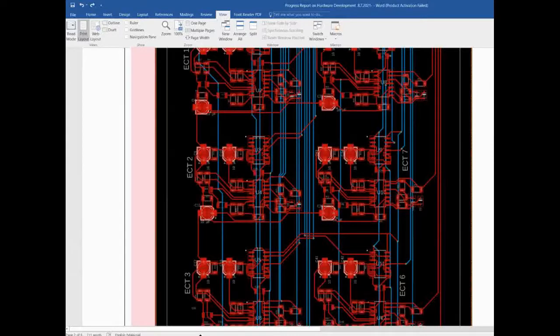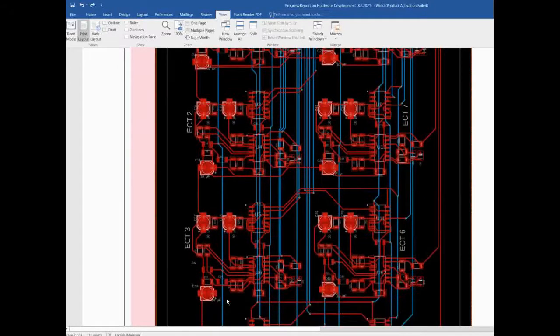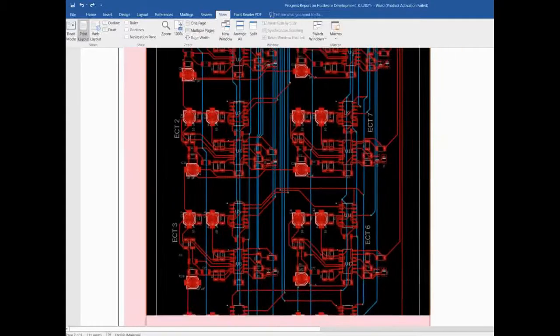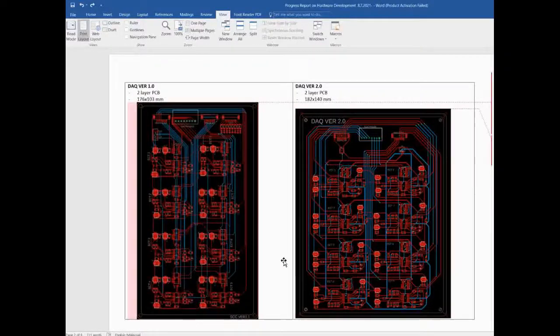I mentioned earlier in the report that there are short circuits in here, and in here, and if you can see here, I have zoomed in, the routing is within the component, and this is the area where the short circuits happen. So it makes sense why there are many problems with my design. So I've been revising the design of the PCB. I have rerouted the traces to avoid any routing within the components.